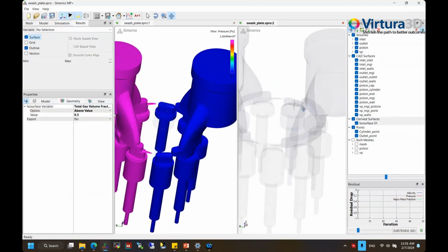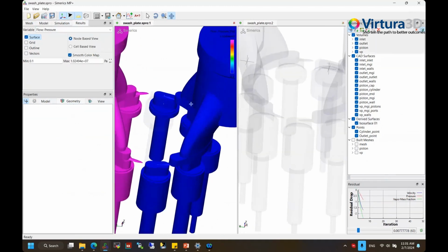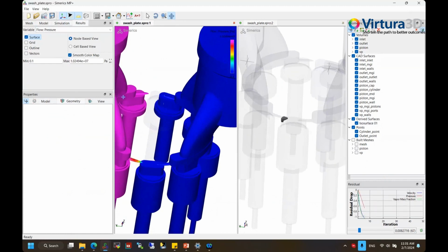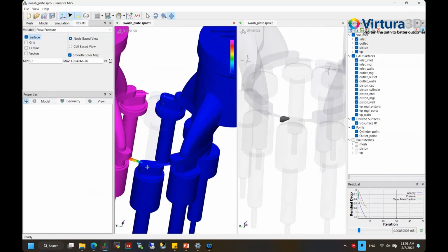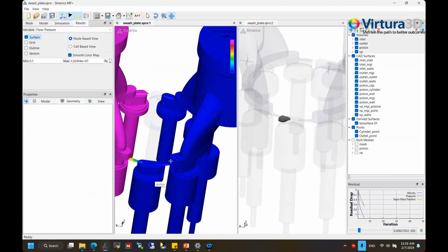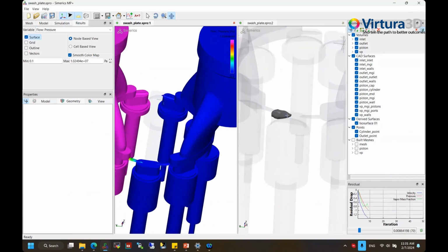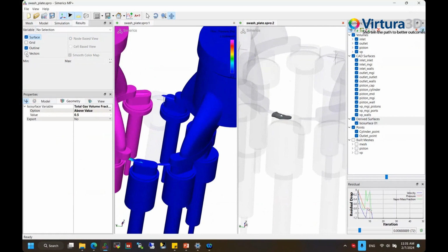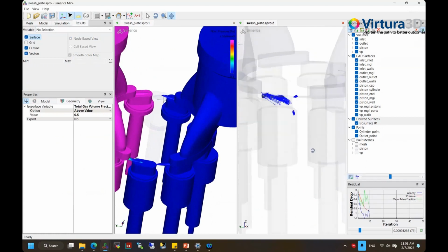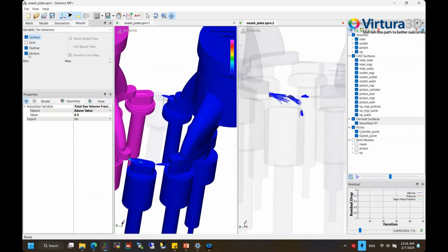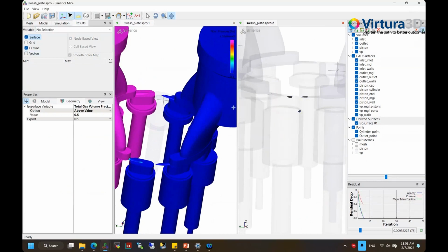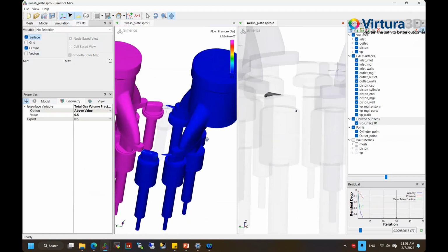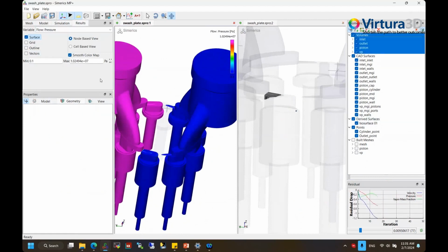As it moves, we're going to see another cavitation happen near this pressure relief groove, when this high pressure discharge port connects with this relatively lower pressure piston because it's not compressed enough yet. You can see there's a large bubble being generated, and if you plot the vector, you will see the vector actually shoots into this piston. You can see how fast it runs. Right now, it already runs a 2-pocket rotation, and pretty much the system already stabilized.